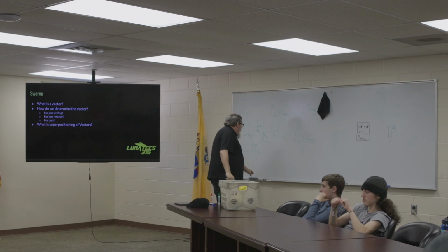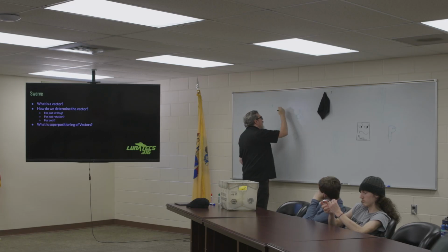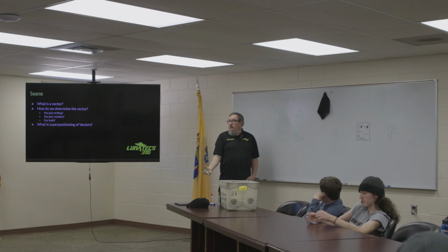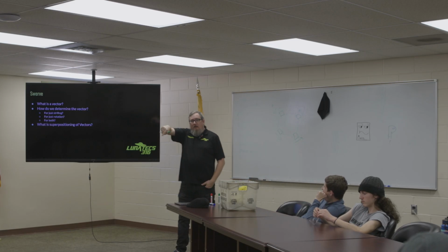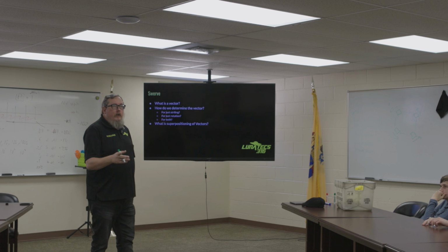Make sense? If I want to turn in place, what is the orientation of my wheels going to be? If I want to turn in place, and then I send power this way, this way, this way, and this way. Does that make sense? And then that will spin my robot in place. So if I want to go downfield and spin as I'm going downfield, how do I do that? How does it work that I could be spinning and going downfield?